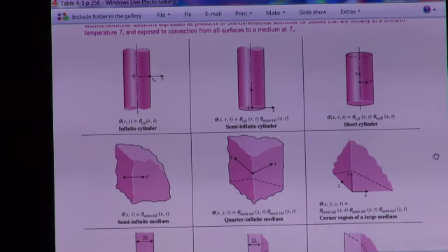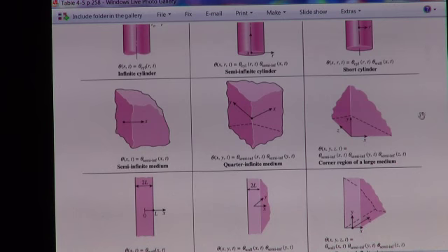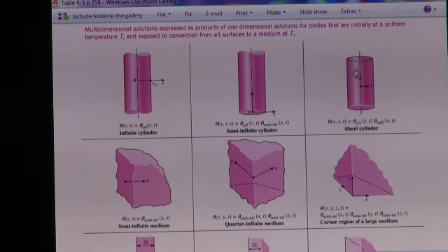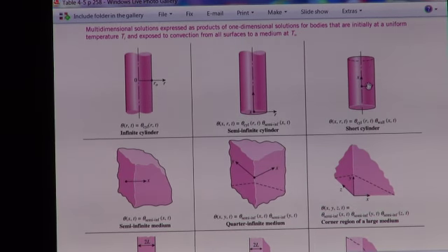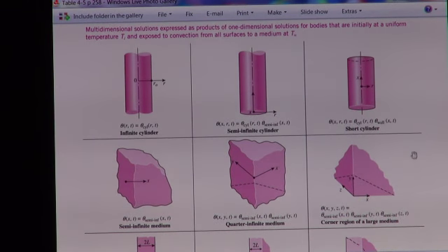In a previous lecture, we specifically looked at the short cylinder. And we have determined the temperature in the center, there at the top and there at that point, after 15 minutes. And we have seen that we actually can get the temperature distribution. What it obviously also means is that the heat transfer wasn't only in the R direction, it was also in the X direction. So it is two-dimensional heat transfer in this case.